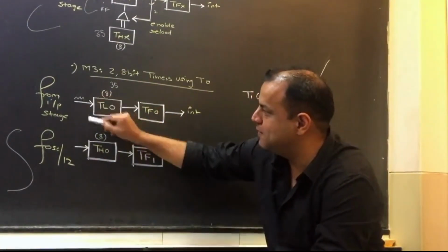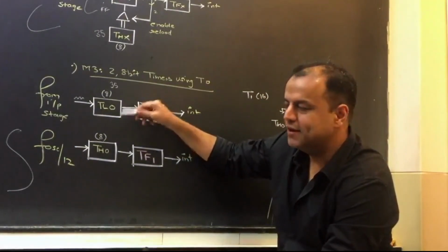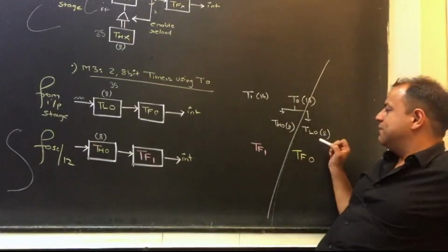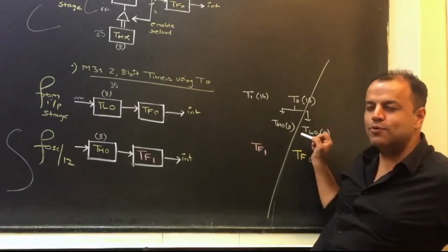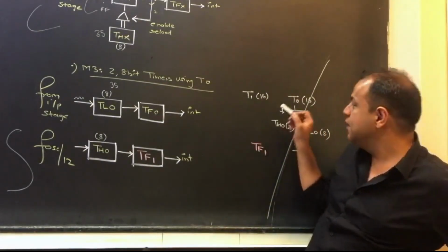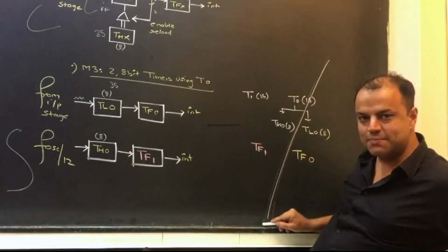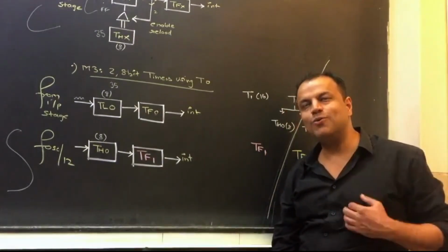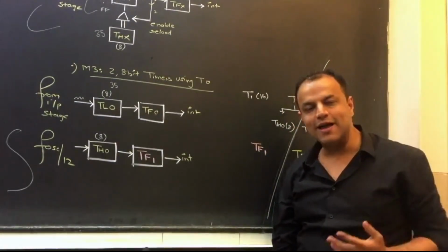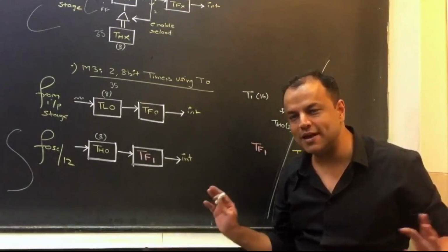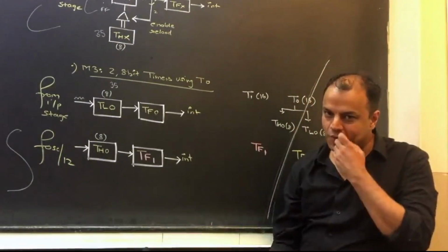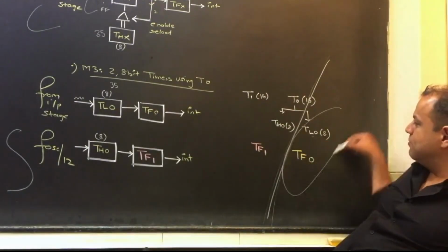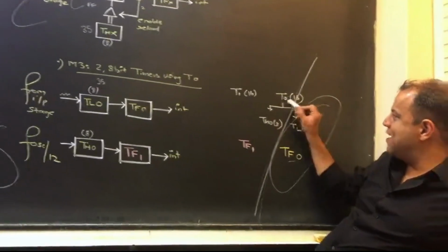On every clock pulse, the lower byte will increment. Eventually it will overflow. Till now, every time the lower byte would overflow, it would go and tell the higher byte to please increment. Now they have become separate. When the lower byte overflows, it is done. Now it wants to inform the processor, look, I have overflown, even I have become an independent timer now. Now what did I tell you? To inform the processor, you need a flag. So very smartly, timer 0 lower byte uses the overflow flag of timer 0.